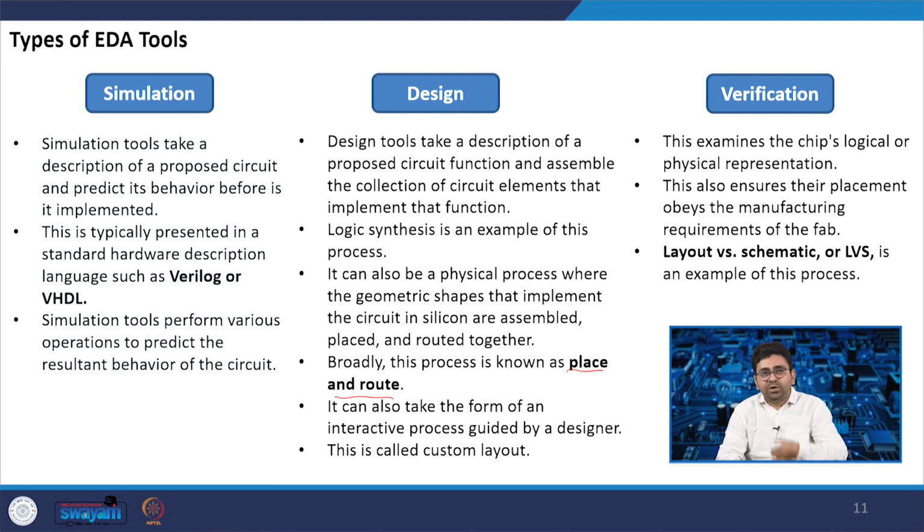There is a possibility that you need to use multiple tools while designing RF circuits, because if you are designing at very high frequency like sub-terahertz, then it is difficult to incorporate all the methods in a single tool. Some of the tools are good in EM analysis, some of the tools are good in circuit design. So, you need to bridge the gap between these and come out with the final results, which should be comparable to the measured results. So, this is how you can use multiple tools to make your RF transceiver design at very high frequency.